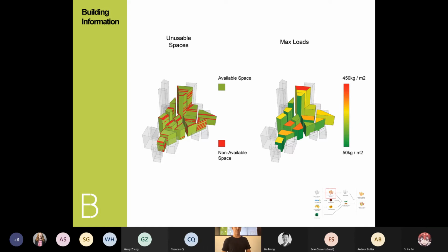Also, plants need soil to grow, and soil can weigh a lot. Discussing with Tony, we estimated that soil weighs around 1,800 kilos per cubic meter, and existing multi-story buildings can take around 400 kilos per square meter of rooftop and 60 kilos per facade. Taking this into account, I populated the rooftops and facades with max loads they can take, just so there isn't something ridiculous like a gum tree suited with a facade space.